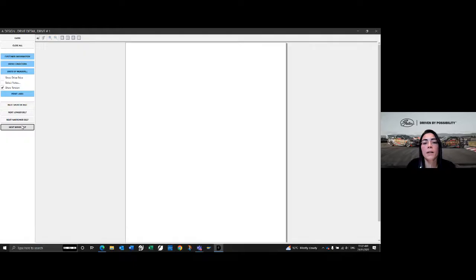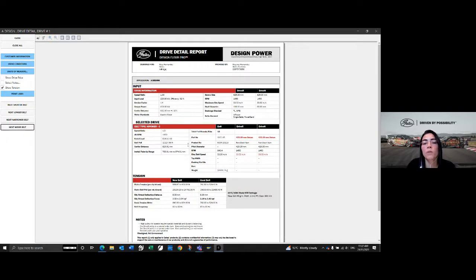Just next wider, and then it will do the recalculation using 13 belts. But still, you may have a problem. You probably cover your rated load, but you have a problem with your pulley arrangement. In that case, you can come back and change your pulley, put a bigger or smaller pulley, and then come back and see. Or in that case, I would probably suggest to just go for a new drive design.